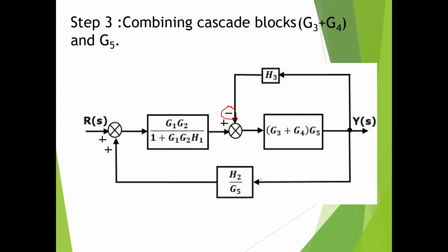If you forget to write plus, minus, and if they don't mention it in the question, you consider negative feedback. That's it. No need to consider positive feedback. If in the question itself the examiner forgets to mention the plus or minus signs at the summing points, you have to assume your own signs, and I would recommend that you always assume a negative sign for feedback. Because if they have not mentioned it, we can assume any sign. So it's a negative feedback.